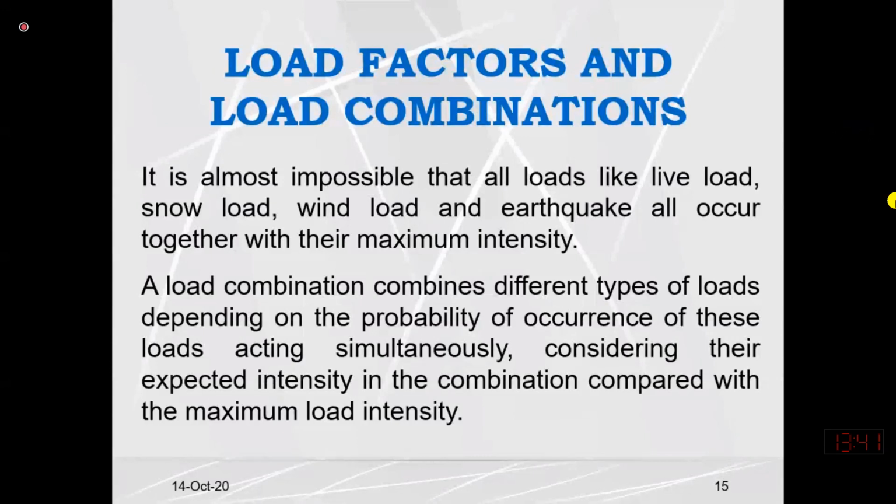An earthquake may occur maybe once in 50 years, and there is no possibility that the earthquake occurs at the same time along with the snowfall, while the building is subjected to the full live load and its dead load is very heavy. It means that if I consider all the possible loads summing up and acting at the same time, my structure will be uneconomical and over designed.